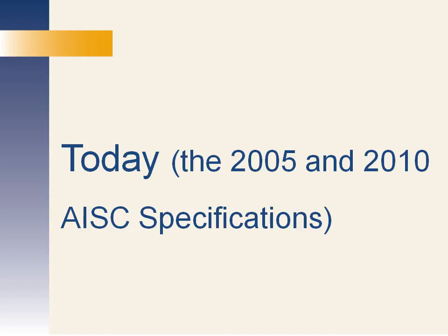We can say thank goodness there was a solution to ASD going in one direction and LRFD going in another. That solution was the 2005 AISC specification that resolved the duality. It unified previously separate ASD and LRFD methods, and we think we did that using the best of both.